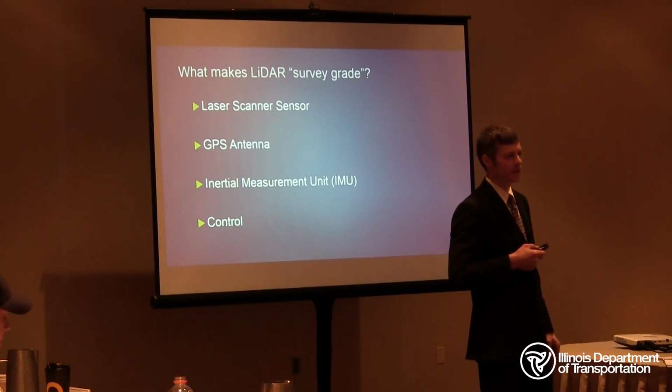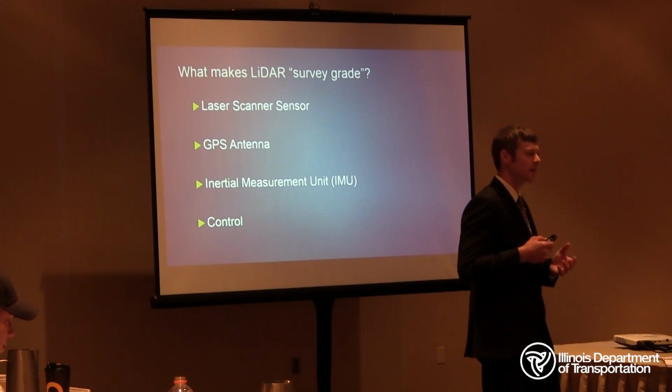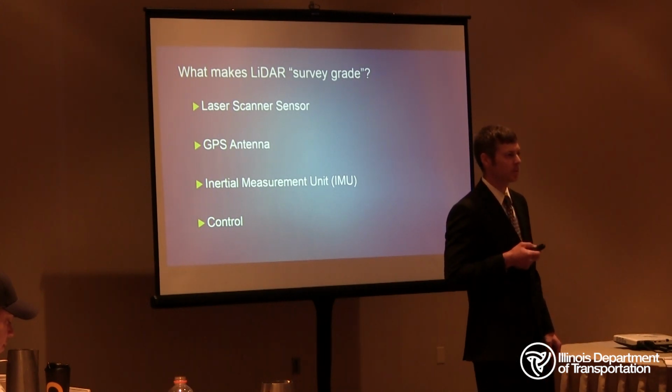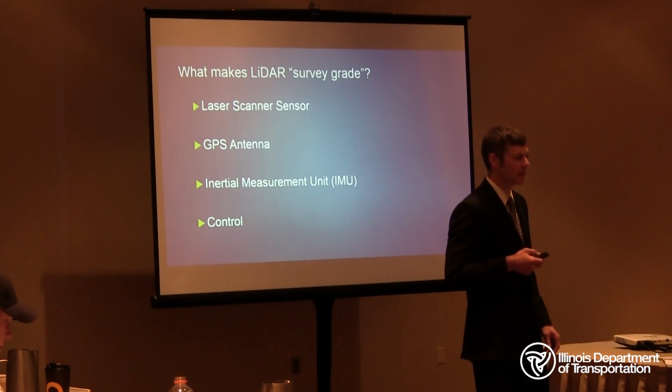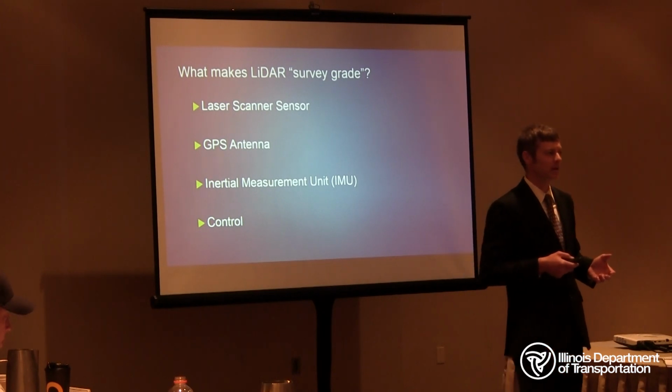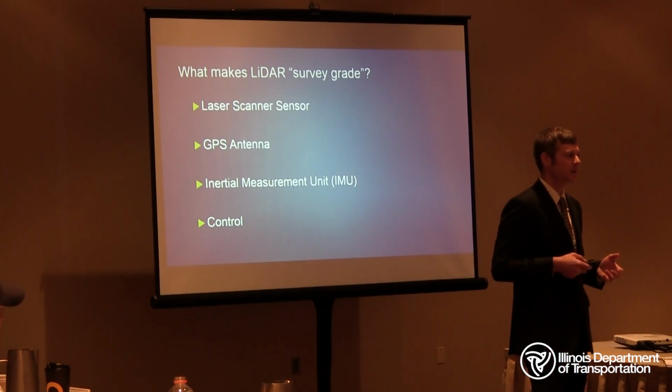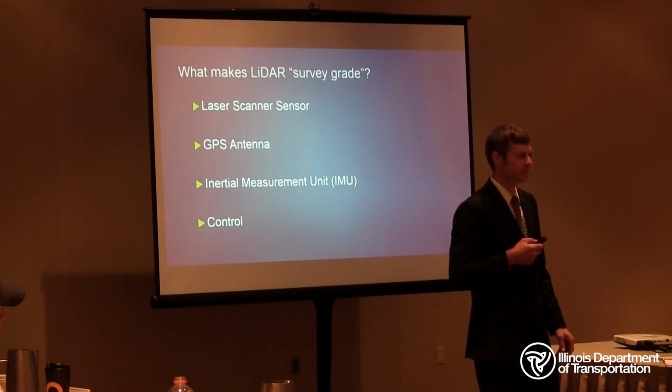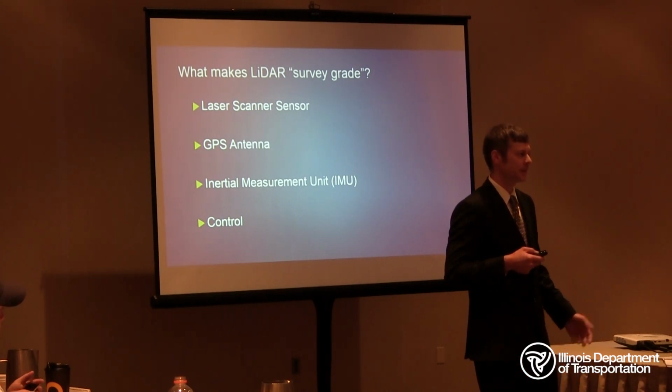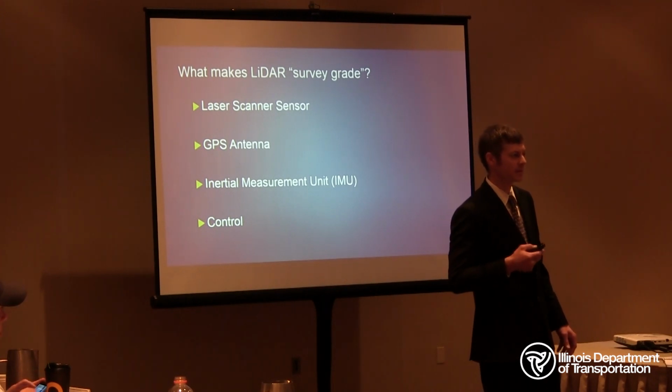So the GPS antenna on a survey grade unit is already configured to receive up to 4 global navigation satellite systems. Many of those satellites have yet to be launched, so as time progresses, we'll see better and more geometry, whereas a mapping grade GPS antenna is typically only configured to receive one of those global navigation satellite systems.